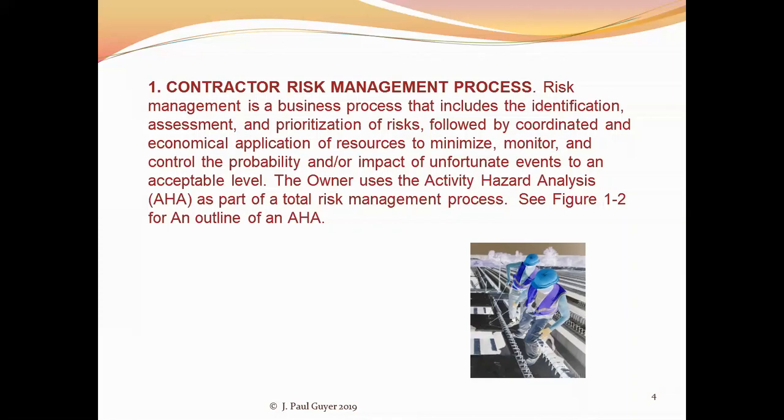So the risks are different, generally speaking, for these different trades. And then an assessment of those risks after you've identified them. The risks on this pipeline excavation project are that the walls might cave in and trap someone in the excavation or cover them up. And so step number two then is assessment of those risks.